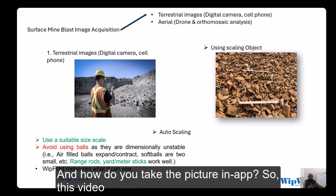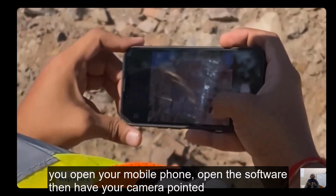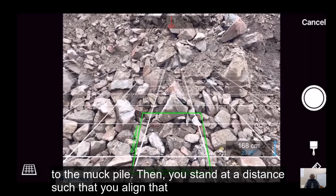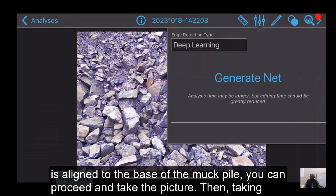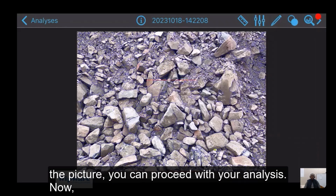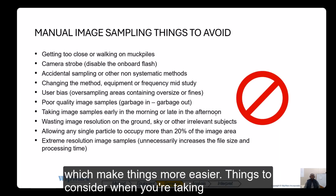And how do you take the picture in app? This video is explaining how to take the picture. When you get to the mine site, you open your mobile phone, open the software, then have your camera pointed to the muck pile. Then you stand at a distance such that you align that green frame to the base of the muck pile. When the green frame is aligned to the base of the muck pile, you can proceed and take the picture. After taking the picture, you can proceed with your analysis. Now in that, you can see the software can easily identify the edge of the material using the auto scale approach, which makes things easier.